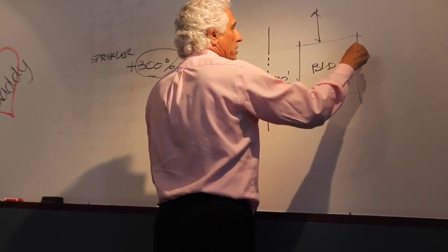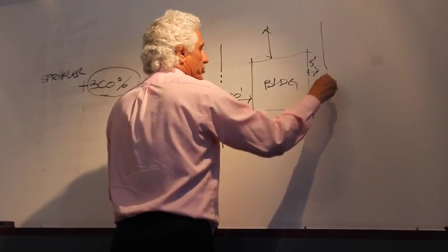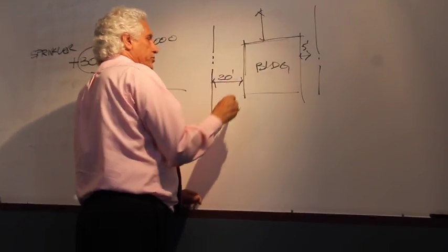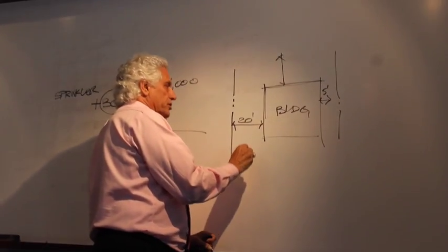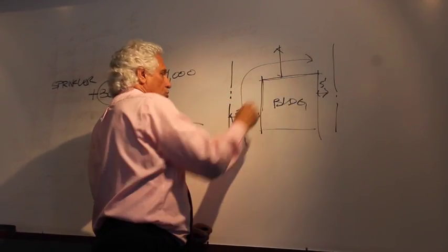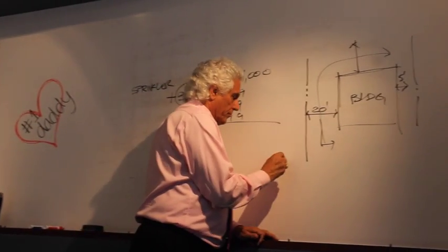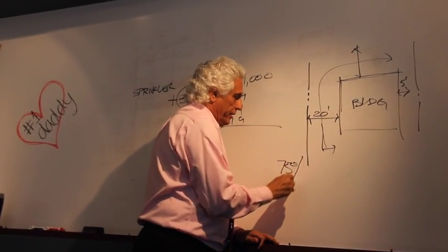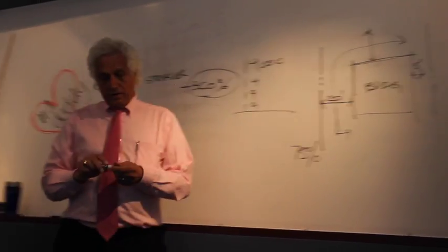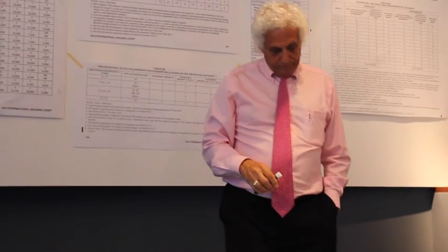But if you have it on one side, it's only 5 feet, you can increase it. The purpose is that this increase allows the firefighters to go around the building. So you can also get up to a 75% increase by having an area increase with 20 feet or more around the whole perimeter of the building.